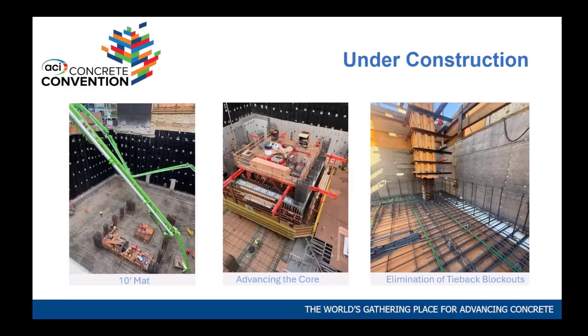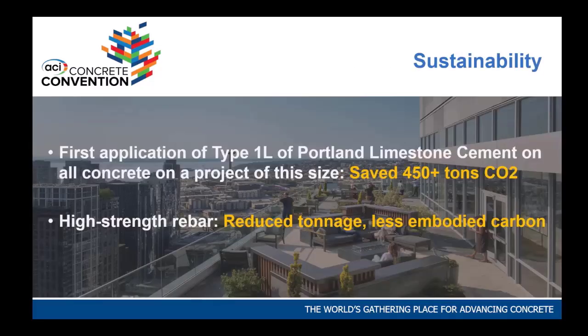The other thing we did is we created these column cages, 2 lifts, so you reduce the number of times you put these columns on site. If you have 16 columns, they staggered the columns. It's a cage that goes 2 levels, so for some of the columns you only have to place half of the column every cycle of floors, because the other one's already sticking up. You do the next one. So it's 2-story lifts, and that works really nicely and speeds up the floor cycles by quite a bit on the typical floors above in the building.